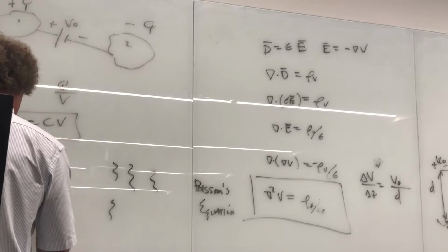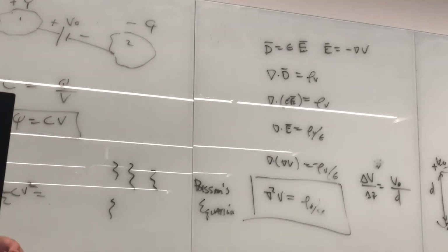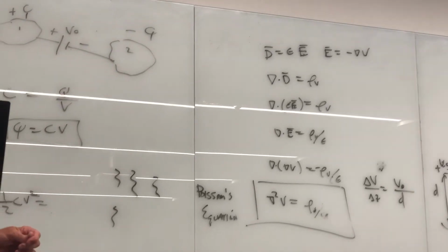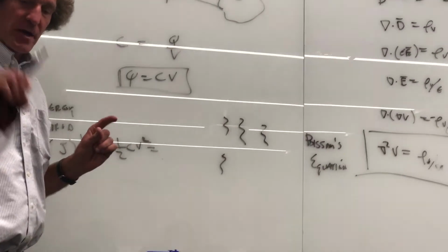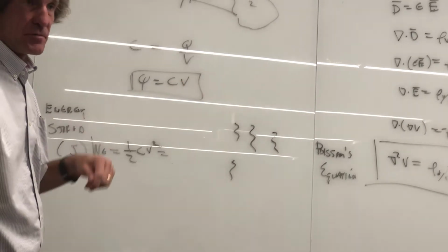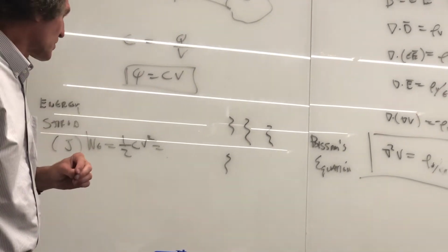It's electrostatic energy, and this energy can be recouped. So if you charge up a capacitor to a value V, you have this much energy, 1/2 CV squared, in it. Now, if you put a resistor across the capacitor once it's charged, you can get all that energy back out. Understand? It's stored. It's not launched electromagnetic energy, it's stored.